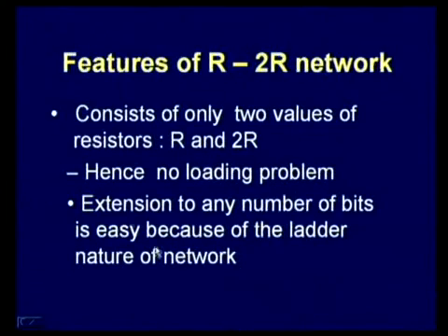Moreover, you can extend the ladder network to any number of bits. If you have a 16-bit digital input and want to convert it into analog form, it is very easy because only R and 2R are put in a ladder form, and you can extend the digital word to any extent. That is another important advantage of this R2R ladder network.